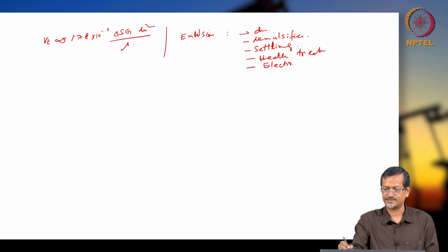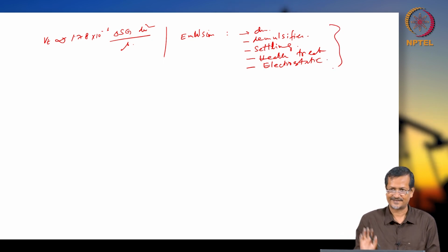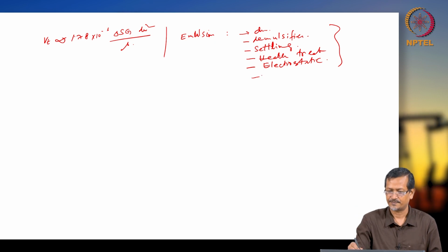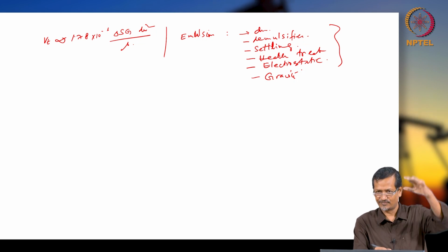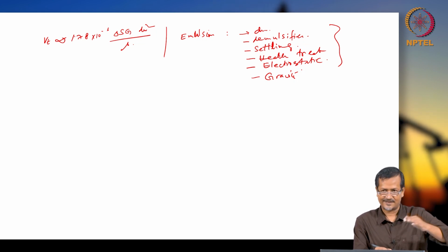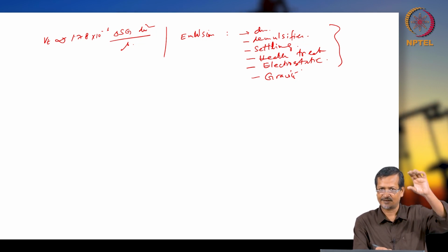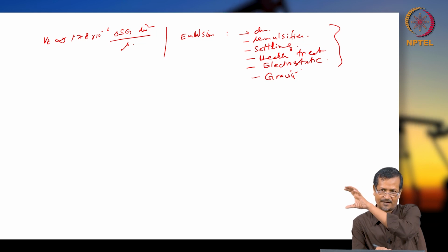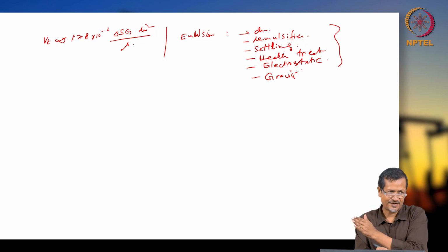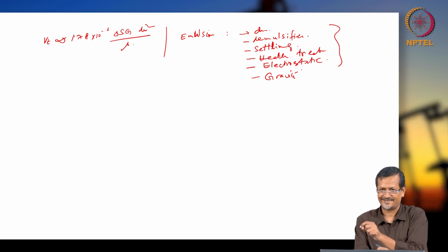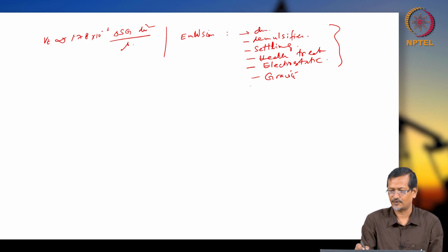So these are key terms actually, whatever we are discussing. Gravity settling is also part of this, right? Because of gravity settling, fluid will be falling down. First level, next level, you are separating oil and water. You are creating two layers, and two layers done. And oil, when you are sending to your gun barrel and stock tank barrel, before that you have to remove water and sediment. So BSW you have to maintain. Then you put it in the tank. From the tank people can take it, you can send it to refineries.